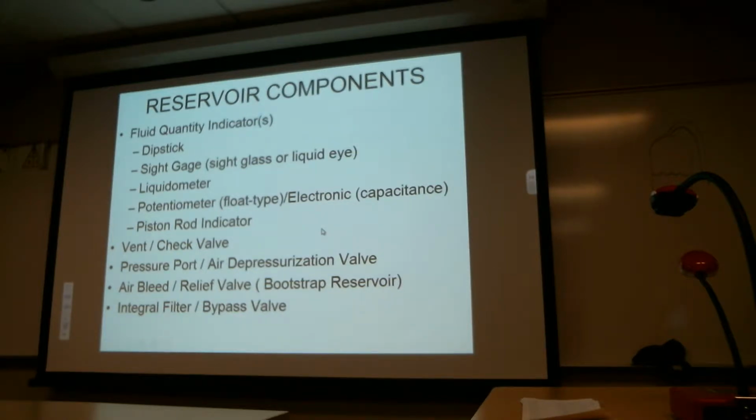One thing to remember is that that filter is filtering incoming fluid. That's the function of it. It doesn't filter fluid at the outlet to the pump. What it does is it filters fluid that has returned into the reservoir. If you want to verify that, you can take a look at the reservoir that we have out in the shop, and you can see that the return fluid is forced to circulate through the filter. So we don't put the filtration directly at the outlet of the pump. We filter the incoming fluid before it gets to the pump.